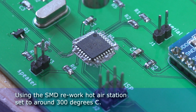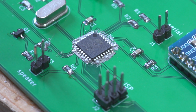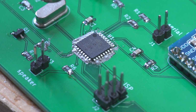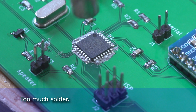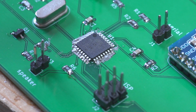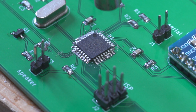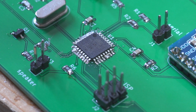And I'm just moving the hot air gun around. Don't stay in one place for too long, or you'll get a hot spot. It's just starting to melt now, if you can see that. It's just going now. You see that? It's quite a bit of copper area to heat up, you know.